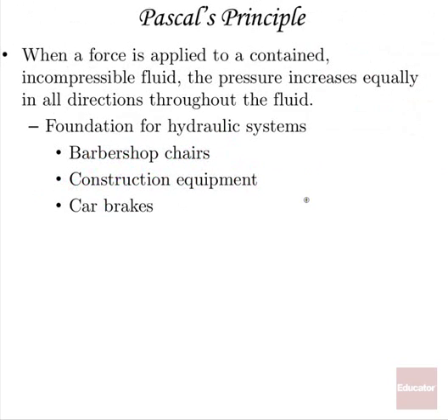So let's talk about Pascal's principle. When a force is applied to a contained incompressible fluid, the pressure increases equally in all directions throughout that fluid. This is the foundation for hydraulic systems in things like barbershop chairs, construction equipment, and even car brakes. In car brakes in the movies, you'll even sometimes see people cut the brake lines so the brakes don't work. The fluid leaks out and the brakes no longer work because the fluid is no longer contained. It must be a contained fluid and incompressible or nearly incompressible fluid.